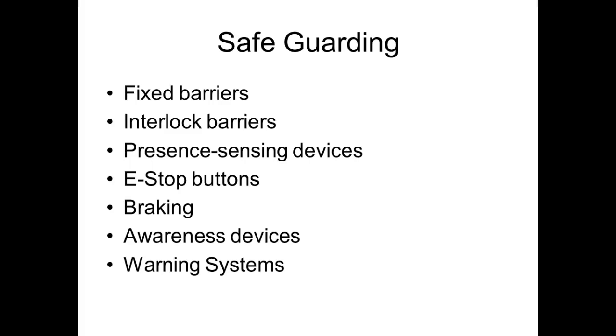It supports what we call full speed pendant. So what that means is I can run it in the manual mode and see exactly how fast it would run if I put that robot in production. So you were watching the robot run at full speed while I was doing it, walking with the pendant. So I was the safeguard.